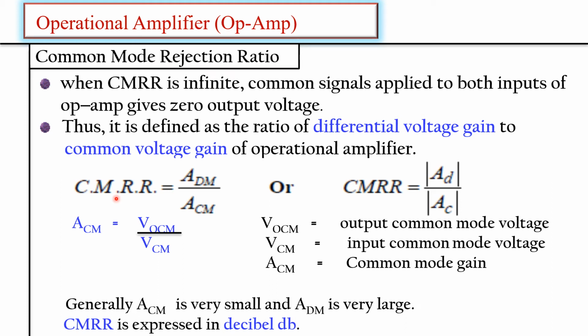So in the ideal condition, in this configuration the output of the amplifier should be 0, but actually if you see, some voltage is available at the output, and this output voltage is known as the common mode output voltage. Because the inputs are tied together and there is a common voltage at the input, which is nothing but noise, it produces a common voltage at the output.